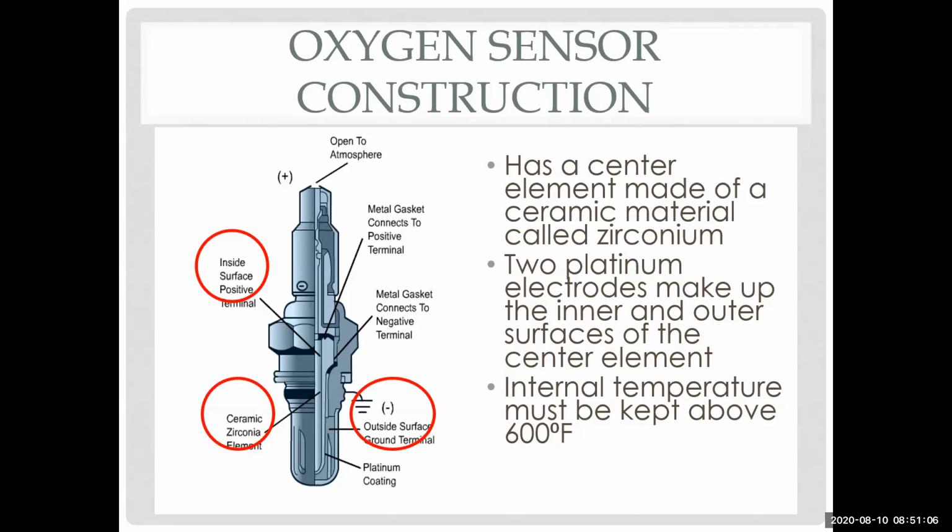So a lot of it's taking the time and, if it's the original sensor, cleaning up the sensor and seeing who made it. Sometimes it's getting a picture of the factory one and then looking on the side of it and seeing who made it for Toyota, Nissan, Honda, whoever. And sometimes you're locked into getting a factory one. And there's a couple applications I will get dealer sensors for. And sometimes getting a dealer sensor can actually be cheaper than getting an aftermarket sensor, and they actually fit right.